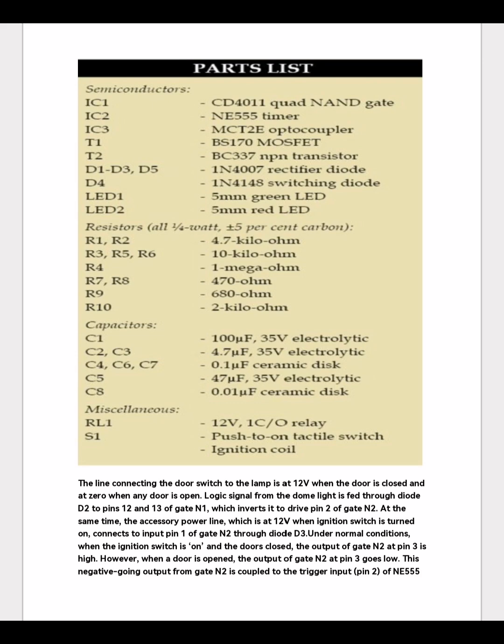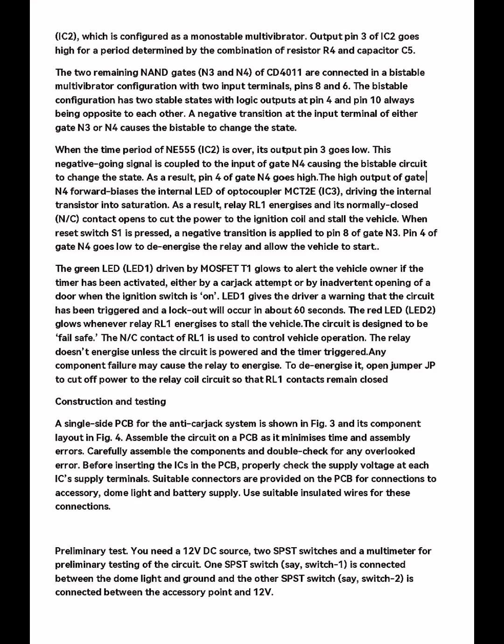This negative-going output from gate N2 is coupled to the trigger input pin 2 of NE555 IC2, which is configured as a monostable multivibrator. Output pin 3 of IC2 goes high for a period determined by the combination of resistor R4 and capacitor C5. The two remaining NAND gates N3 and N4 of CD4011 are connected in a bistable multivibrator configuration with two input terminals, pins 8 and 6.